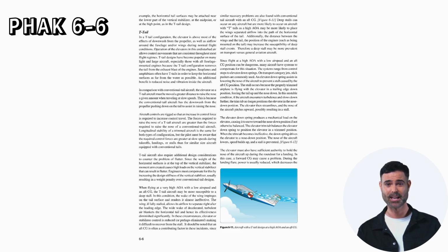Since flight at a high AOA with a low airspeed and an aft CG position can be dangerous, many aircraft have systems to compensate for this situation. The systems range from control stops to elevator down springs. On transport category jets, stick pushers are commonly used.